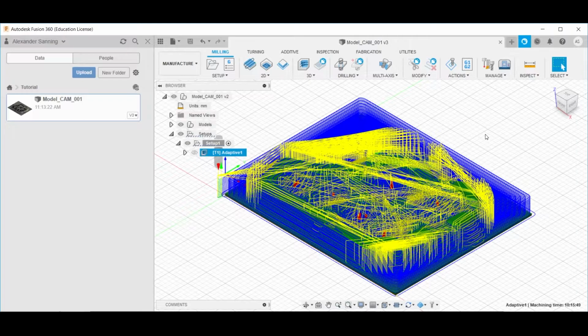The aim of the roughing toolpath is to minimize the amount of material that the finishing toolpath has to engage in, so as to make sure that the finishing toolpath, which often uses a tool of a relatively small diameter, can properly define the final surface texture without hiccups.